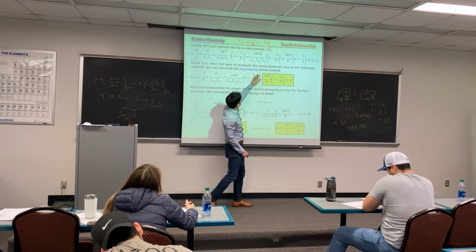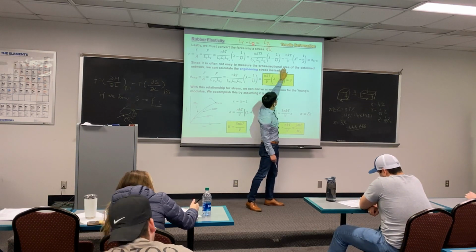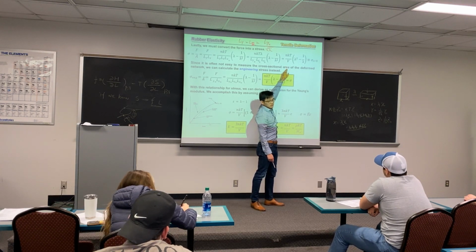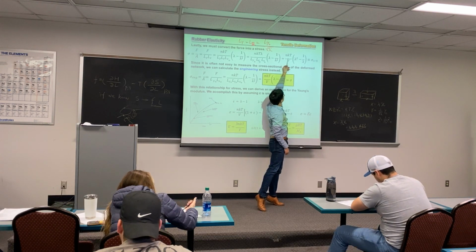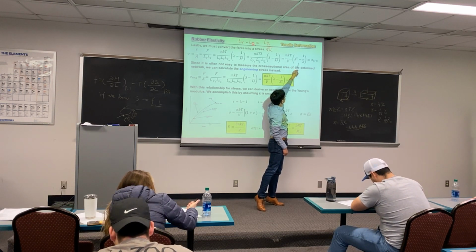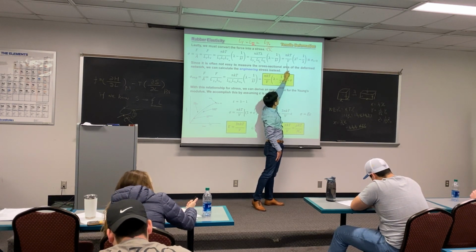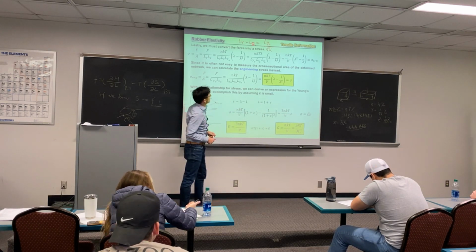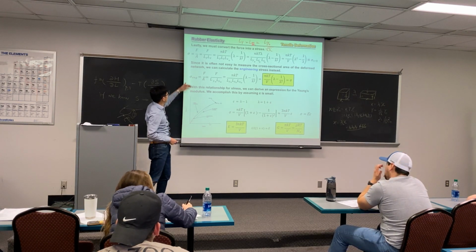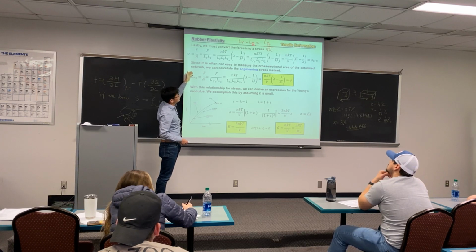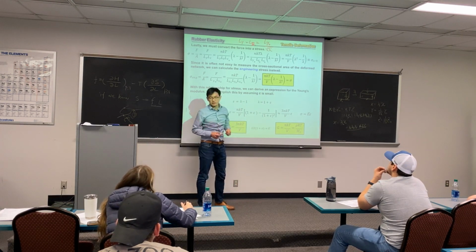So you can get all these initial terms. If you multiply them together, it will be the initial volume, x, y, z. It will tell you the volume. Number of strands, kT, and lambda square minus 1 divided by lambda. This is called the true stress in the deformation. We can predict it. Well, there's another term called engineering stress, and everybody knows the difference is basically a factor of draw ratio. This will be the engineering stress.